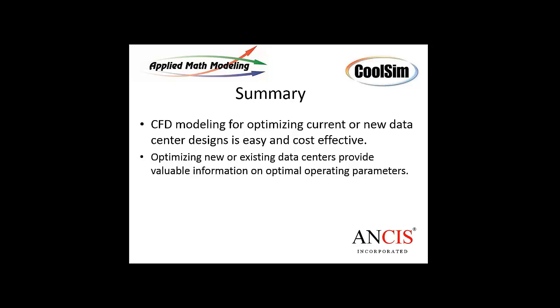Easy enough to do in CoolSim. We make it very fast and easy for you to lay out where the wattage is in the rack. So I usually divide pretty evenly. You don't have to kill it in terms of detail to get good advice out of these systems.